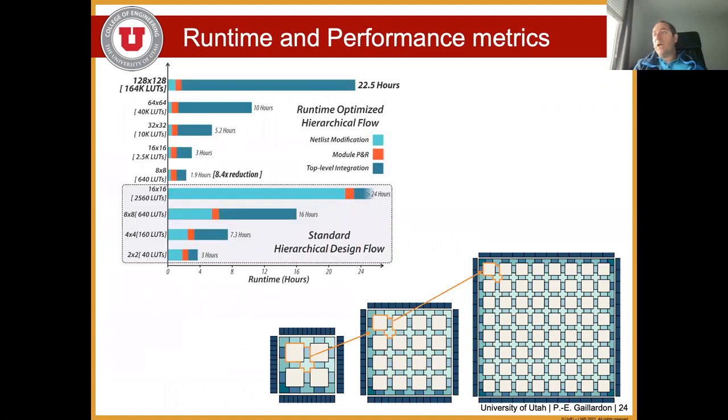This is very important, and this is very unique again to FPGAs, because if you're using a standard methodology, which by the way is what other FPGA generator projects do, you get hit very quickly by an exponential wall coming from your design flow. If you look at a tool like ICC2, because of all the loops you have in your FPGA and all the constraints in terms of routing and performance and symmetries, everything explodes very quickly, making fabrics as small as 2,000 LUTs infeasible